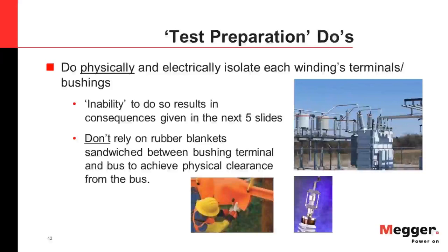You drop these two side bars and are left with a tiny insulator separating the transformer from the still connected bus. And then you'll attach a guard lead to the top of that insulator and continue with your measurements to effectively guard out any contribution from leaving bus connected.